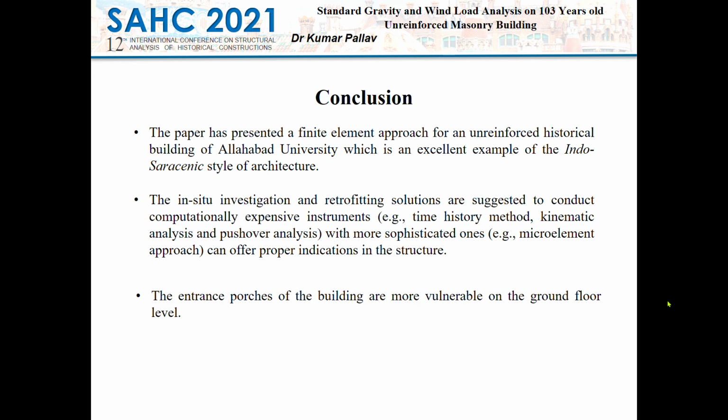Further, in situ investigation and retrofitting solutions are suggested, and computationally expensive methods such as time history, kinematic analysis, and pushover analysis will give, you can say, a clearer picture of the present condition of this structure. Further, I also would like to conclude that with this particular work we found that the entrance ports of the building are more vulnerable at the ground floor level.